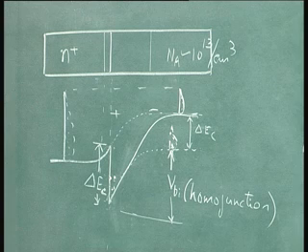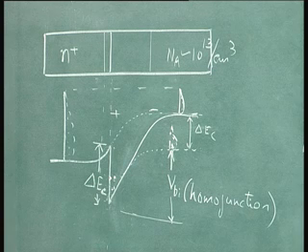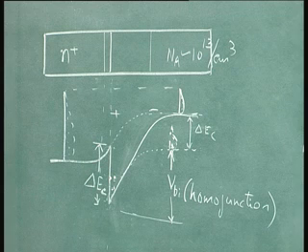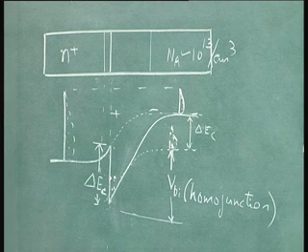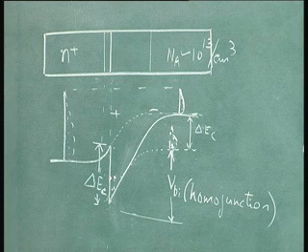You have better and better techniques, you could go down to 77 degrees Kelvin and get a mobility as high as about 10 to the power 6 centimeter square per volt second. You will not believe it. At 77 Kelvin, 10 to the power 6, okay, that sort of mobility you can get. 10 to the power 5, quite comfortable. You can get at liquid nitrogen temperature, but at room temperature, you are stuck with this curve. At room temperature, the best that is reported for gallium arsenide is 8500 centimeter square per volt second.